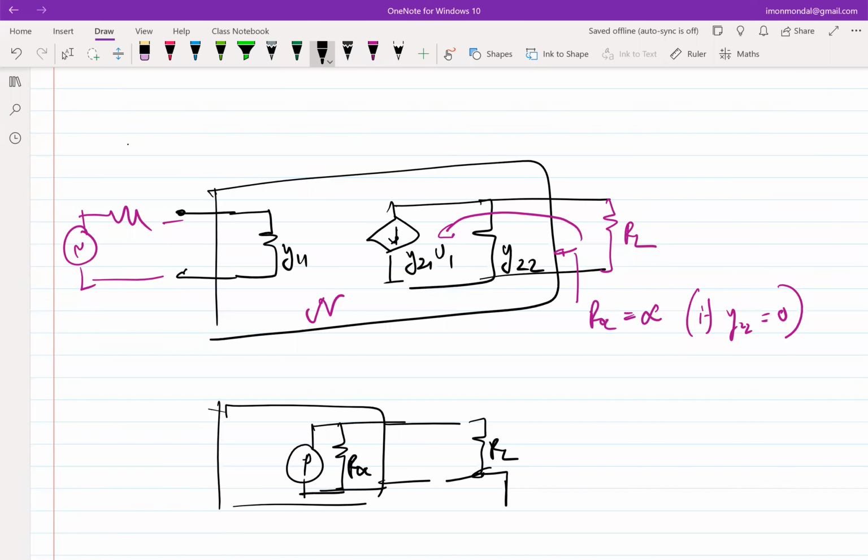As far as a voltage source, I assume that is easy to understand, easy to visualize. In terms of a current source, the same definitions go with respect to current. All the current should flow into RL regardless of the value of RL. Which means you change RL, you don't want any current division. In reality, there will always be a current division, right? So in reality, this current is IOC, or in this case, let's say ISC.